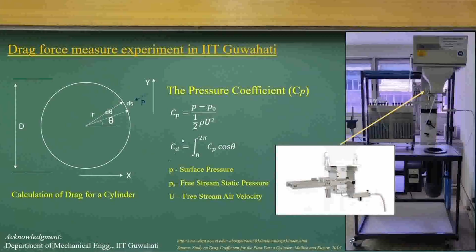Before that, I just want to show you an instrument which can measure drag force, an experimental setup like this, where you can compute the pressure coefficients, and if you integrate them, you will get the drag coefficients. That way, when you put cylinders, you can compute the force acting on these cylinders with varying air flow conditions.